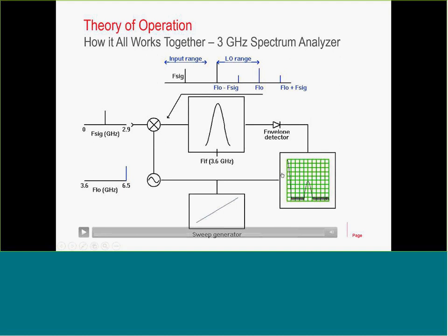Might be able to take it away, but it has been there, and people kept it because that's a big indication of where your 0 hertz position is on your display. So when you see a big signal, that's 0 hertz, and from that point you can move versus frequency, and then you can get your signal.